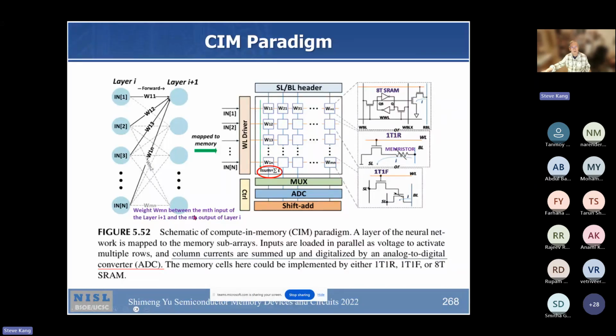So that's how you can have a crossbar array, and you feed input, and then you get multiplication and the sum. The I sum is a sum of all these individual currents, which happens based on Ohm's law, that is a multiplication. So the multiply and accumulate, MAC operation, is happening in every column here, right?